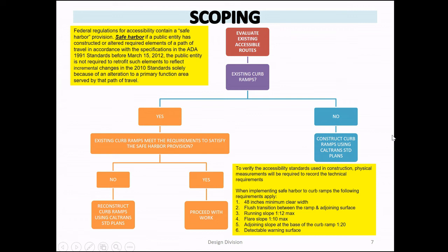As a practice, I usually add them if it's not too much work. Like if you were to relocate those pedestrian pads, probably not. But if it's a very easy fix, I will put them in there as a refuge. Well, the issue here is that you can put in a curb ramp, and it has no connectivity to anything. Right, but you can use it as a refuge. They're going across the street in a crosswalk, they go there, they push the button, they wait for the traffic to clear instead of waiting at the corner. It's totally up to you.